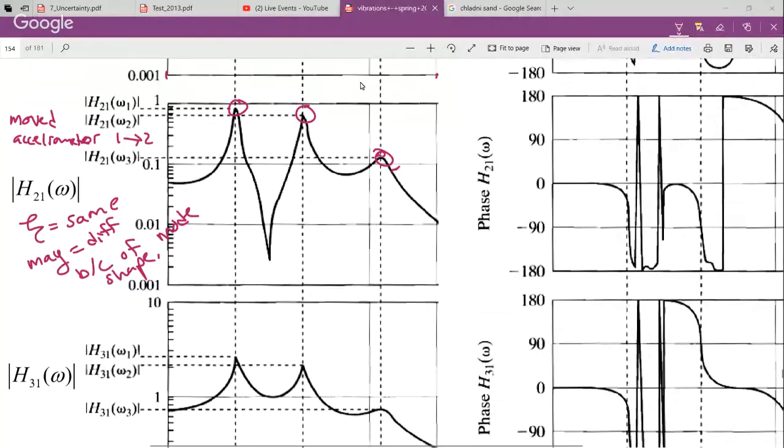Let's just take it now. You've got to move the accelerometer. You've got to move back to your response. Or better yet, if you had three accelerometers to begin with, in one hammer, you could get all your data measured in one set. You wouldn't have to move and measure the response at three locations.